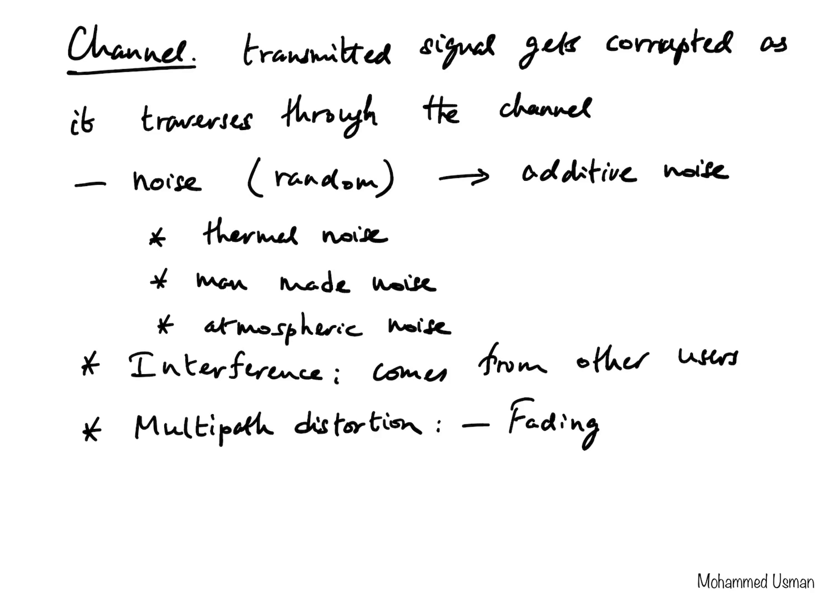And that happens because there are multiple components of the same signal reaching the receiver, each having a random phase shift. If the phase shifts are 180 degrees apart from each other, then they will cancel out each other, making the signal become zero.